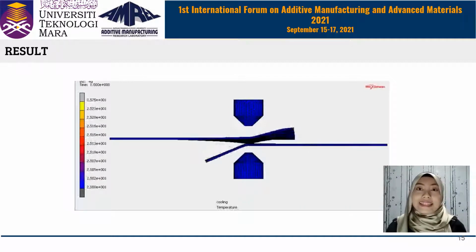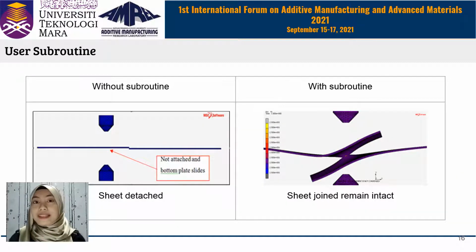Then we can see that at the end the plate was flat. It is because there is the presence of tensile in the process. Then, when the metal sheet was subjected to tensile load while the weld nugget was still in contact in a tensile test process simulation, it flapped at the 41st increment. This study reveals that the increment has not converged, indicating that the simulation has reached its maximum stress limit.